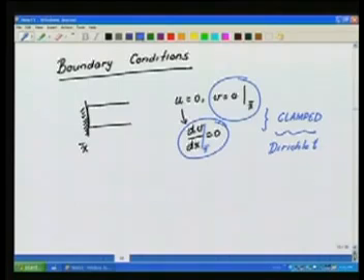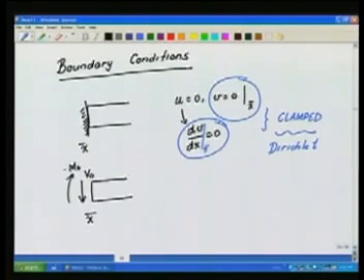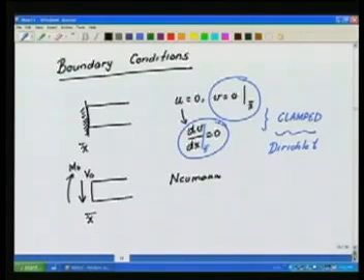We can have a mixture of things also, let us see. So we can also have a second type of boundary condition at this point end, where I am specifying the bending moment and the shear force. Okay. That is, the bending moment and the shear force are given. So this is our Neumann end. Now it could be the bending moment and the shear force could be 0, which corresponds to a free end. So this is a Neumann boundary condition.